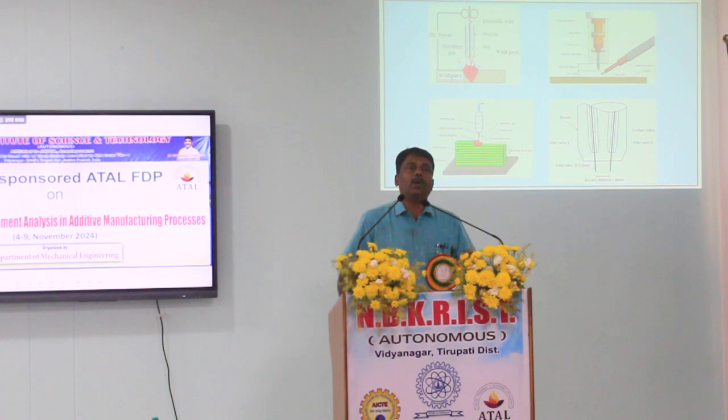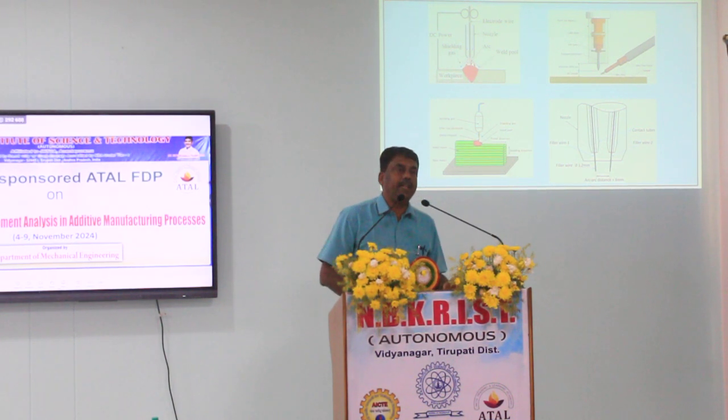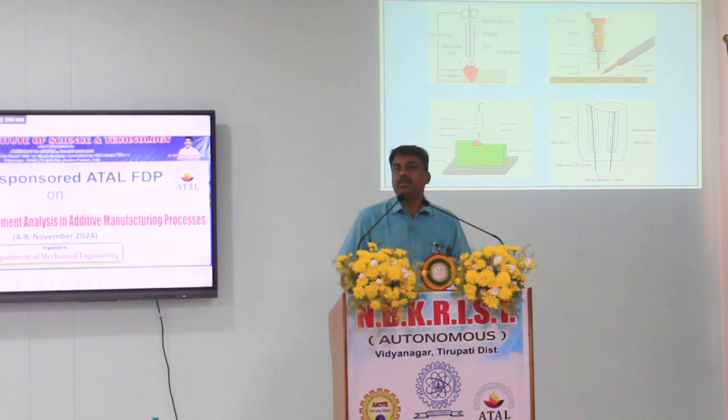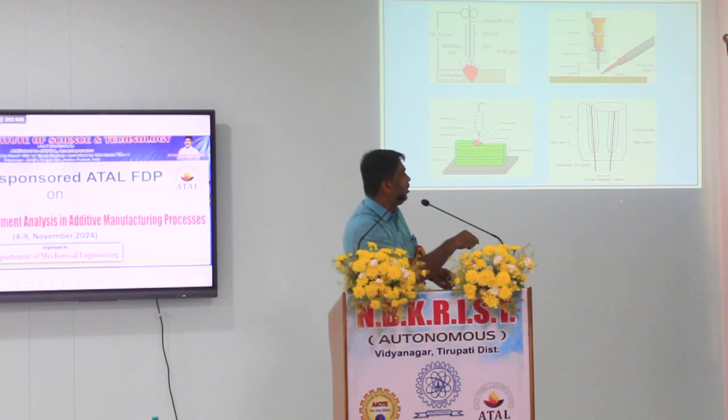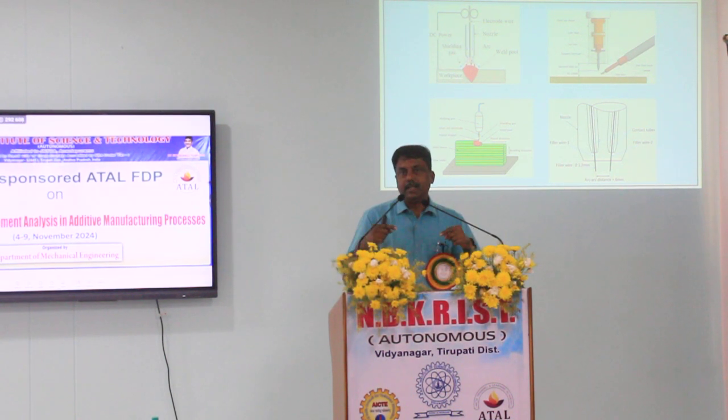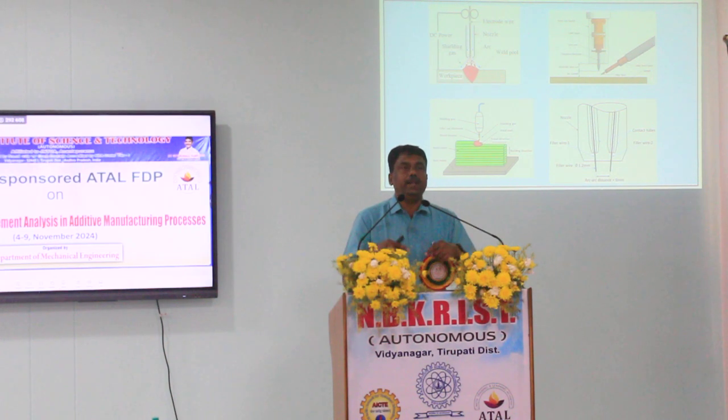Right, so there are a lot of advantages of this process compared to powder-based processes. Because here we use a very heavy heat source, you can also melt much more than powder-based processes. So imagine if you use a dual wire, what I showed here, 2 wires, we call it tandem MIG. 2 wires simultaneously we can feed. We create a large molten pool.